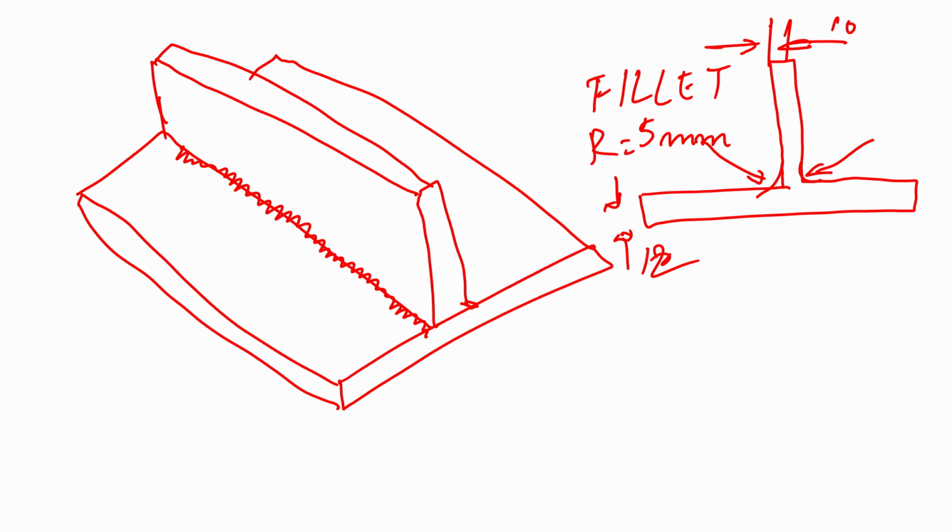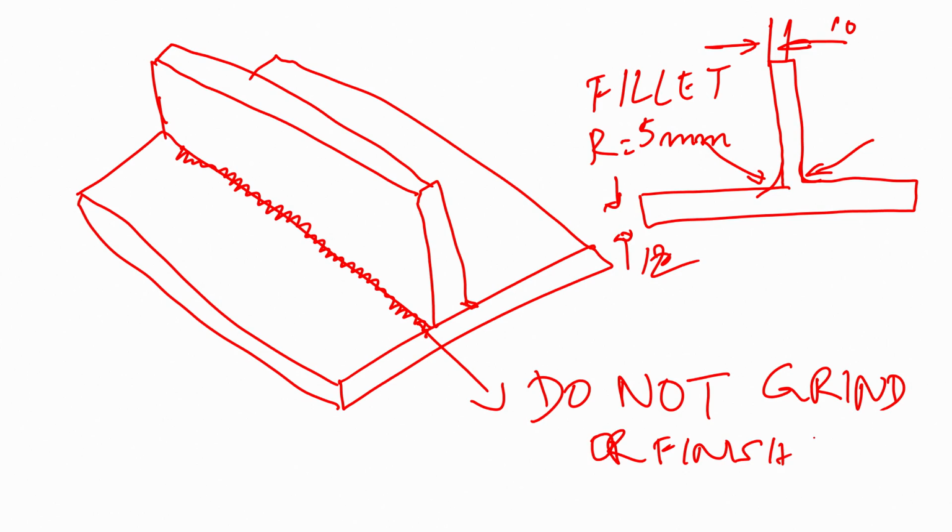Especially in the case of welding, let me repeat, they usually write this, because this seems to be very important. Once a weld is there, you should not dress a weld or grind it, because it is likely to create some problems. However, the person carrying out the job, the welder, knows how to achieve these things. So, he will try on a trial piece and then achieve it, and it is not just enough if you write it as 5 millimeters.